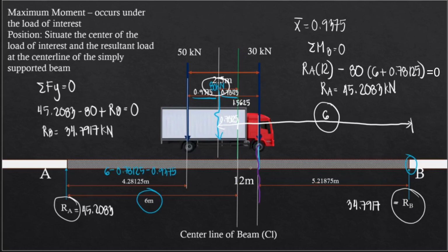the 30 kN load. Now if I consider from the left, then the positive effect will be counterclockwise, while for the right side, the positive effect will be clockwise. Now this will be important. Both of these would be the moment under the 30 kN load.